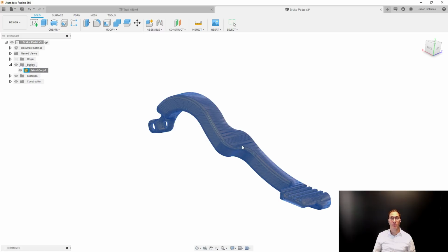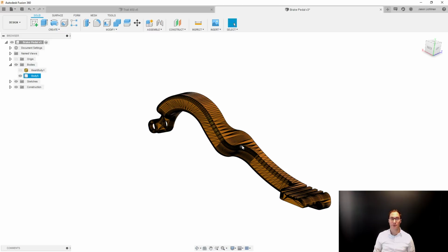Let's hit that OK button. And in the background, it's doing a conversion from one way to define the geometry to another. Now I have a BREP solid. You can actually tell that it's a solid because I have this gray cylinder icon as opposed to the mesh, which has this yellow icon with kind of a mesh going across it.